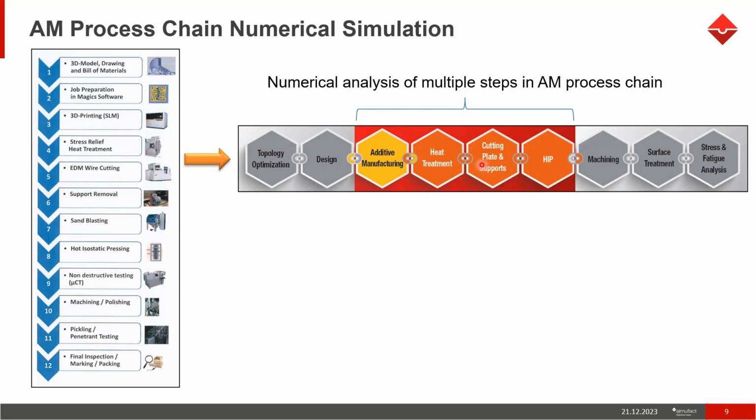Yes, we can check that. So that is done in this additive manufacturing part, where we will check whether the manufactured part is going out of the tolerance. So there is something called distortion compensation. We will take our initial CAD design and superimpose our manufactured part onto the CAD, and check how much deviation there is between the CAD and the manufactured part.